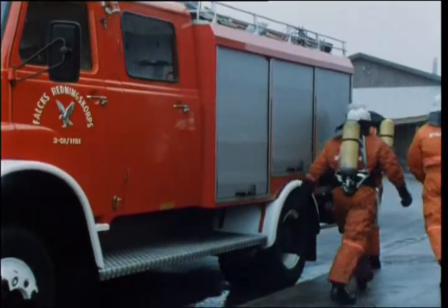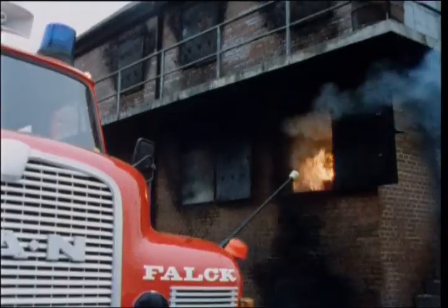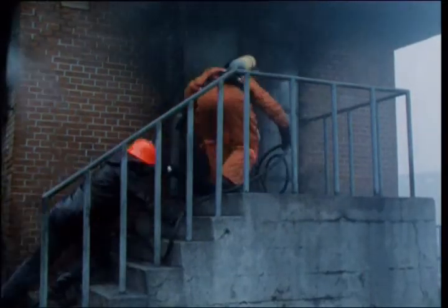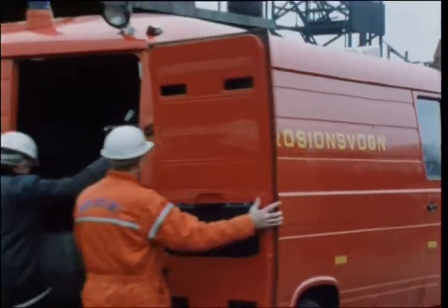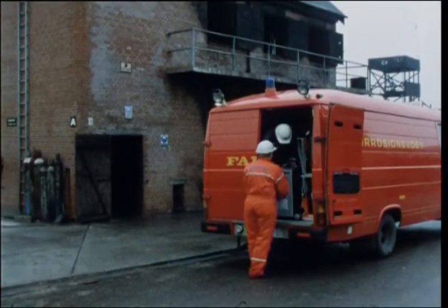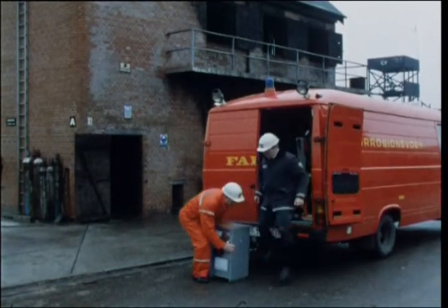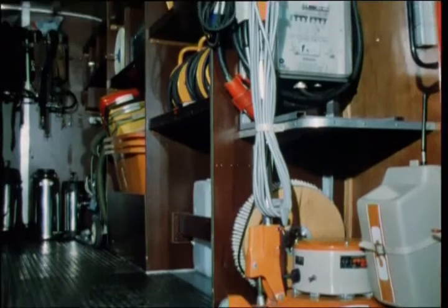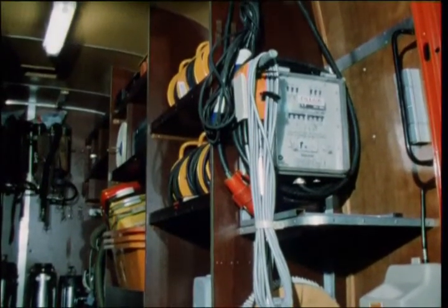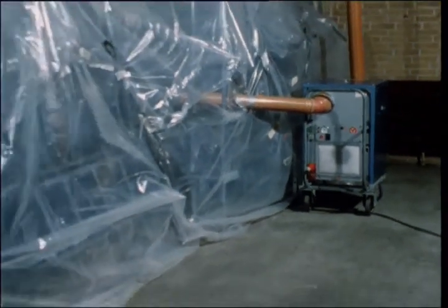After a fire, damage to machinery and equipment from corrosion comes from the water used to extinguish the flames. So here, an inhibitor is added in the last damping down by the hoses. Drying out is then essential for preservation. The corrosion wagon carries an air drying machine and all the necessary equipment to help prevent rusting. Important items are covered and connected to the dried air.